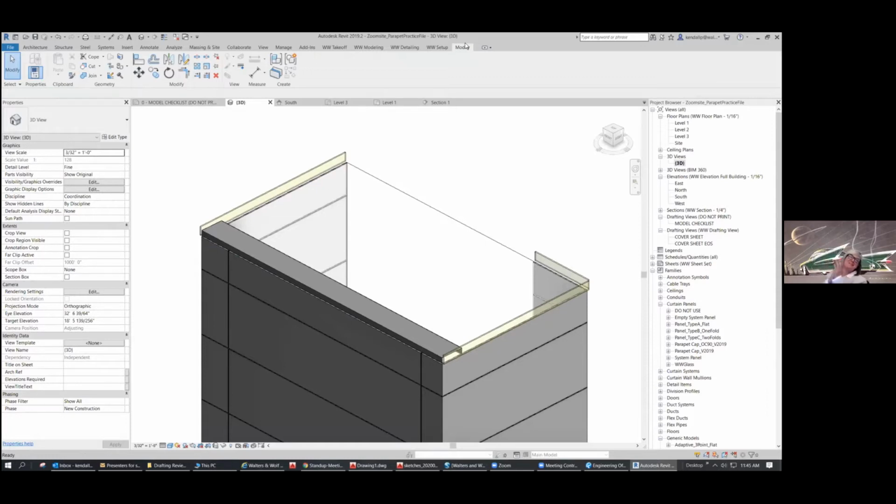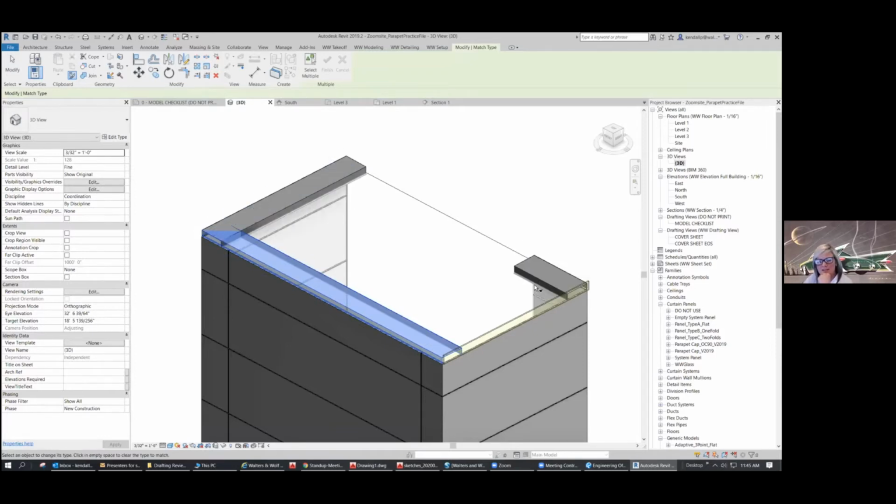Oh, sorry. Okay, I wasn't sure. I didn't realize you're talking about the parts now. Yeah, you still have to go through. We've just done the walls. Correct, that's right. It's tough to manually add. For some reason, it looked like those just magically appeared, but okay, I got you. Let's do match properties here like you wanted, but this time let's grab the family. So go back to your match properties command, hover over that and tab until the part highlights. Okay, perfect, select that. Now select and tab over that. Oh, I missed that part. All right, sweet.